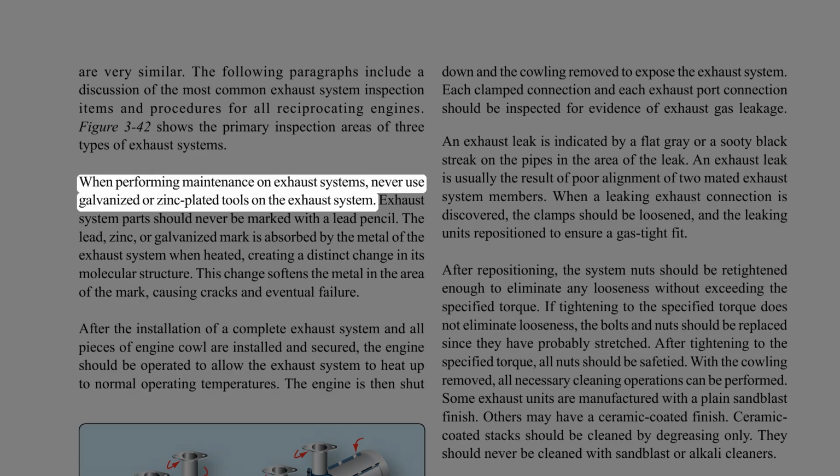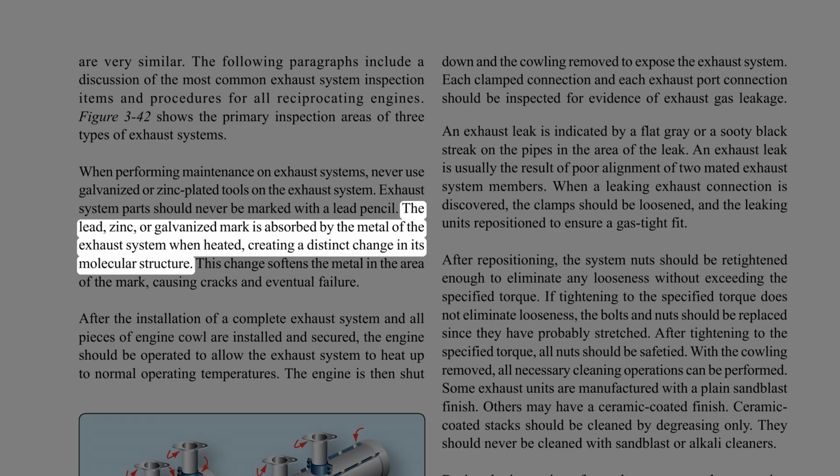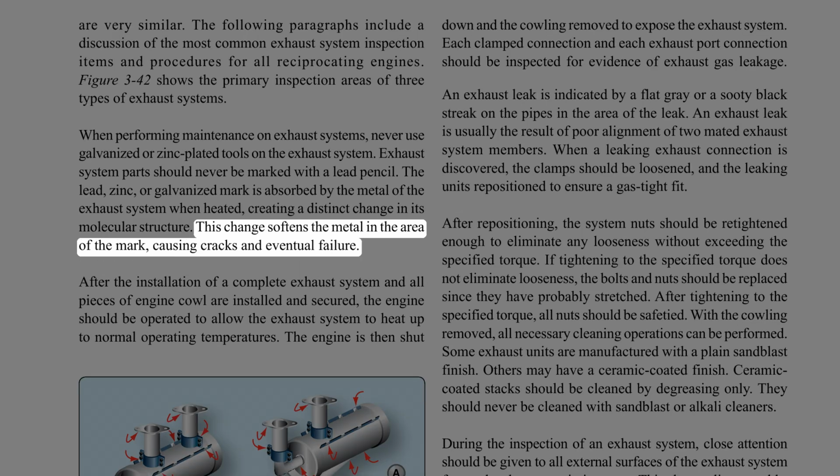When performing maintenance on exhaust systems, never use galvanized or zinc-plated tools on the exhaust system. Exhaust system parts should never be marked with a lead pencil. The lead, zinc, or galvanized mark is absorbed by the metal of the exhaust system when heated, creating a distinct change in its molecular structure. This change softens the metal in the area of the mark, causing cracks and eventual failure.